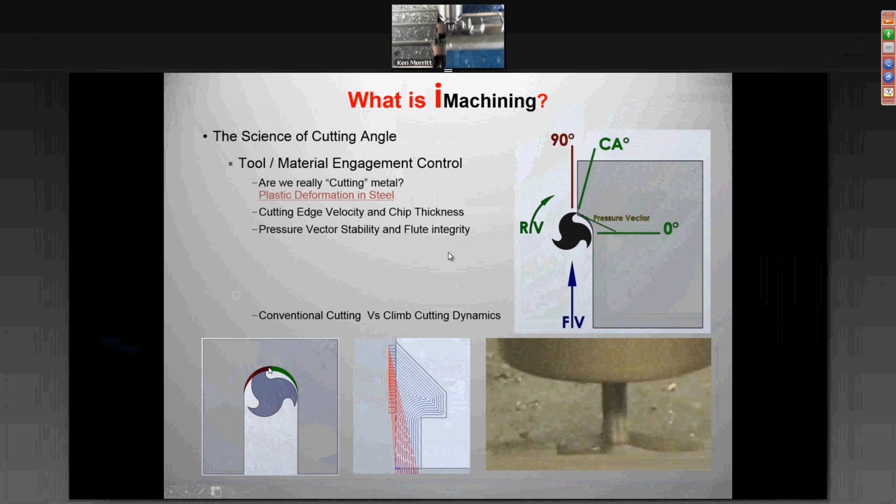Also, because of that pressure that's being applied in a linear fashion, we've never really been able to cut very deep with a tool, because that pressure goes up exponentially with the increase in depth of cut. And that's why we wind up breaking tools off all the time. So we're doing several things very, very different in what we're doing here.